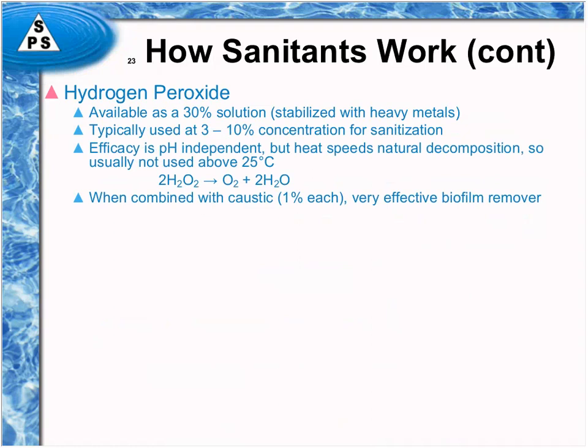Its efficacy is pH independent. In other words, you can adjust the pH, combine it with caustic, for instance, as shown there, and you'll really goose up its activity. But if you try to heat it, you'll decompose it. So it's often used at ambient temperature, around 25. It's got a half-life, once you've diluted it, of about